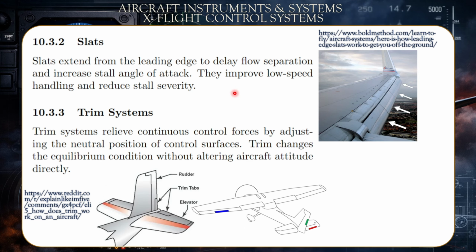Of course, there is a drawback, which is increased drag, but you don't mind having increased drag during takeoff. Meanwhile, in landing, the slats and flaps are extended in order to increase the drag intentionally to slow the aircraft down, but at the same time, it uses part of the airflow to generate lift and lower the descent rate so that the touchdown would be smooth.